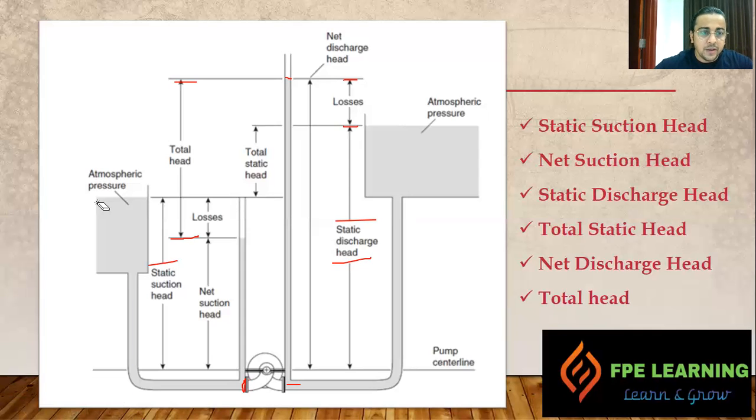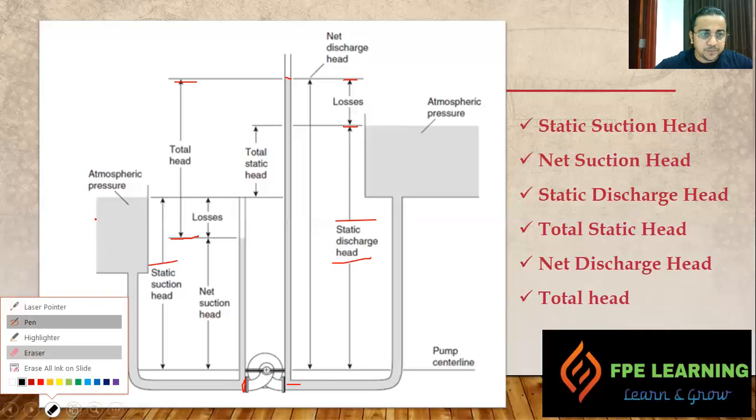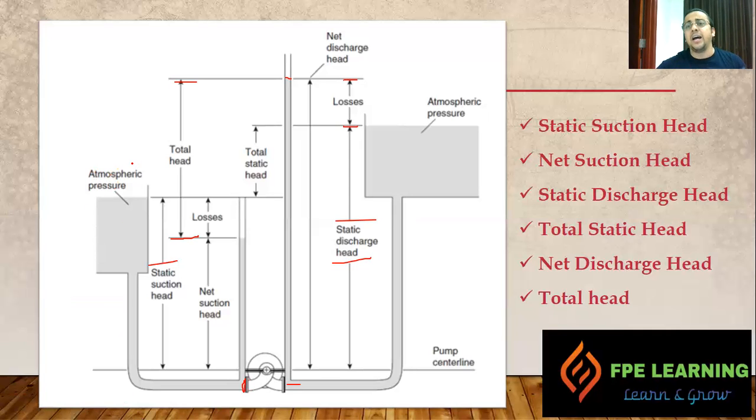So here we have, just wait a moment. Here we have an atmospheric tank. Here we have a water tank, and due to the height of the tank, we have some pressure here, right? In feet or in meters, we can convert to psi or bar as convenient, based on different formulas. And now all the way from this much pressure here, by coming to the inlet side of the flange, we lose some pressure because of the friction and all. So it comes to the impeller of the pump, and the pump adds some energy, pressure, and then it is going all the way up to this one.